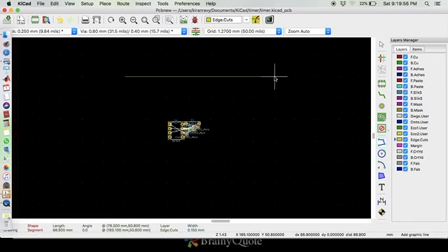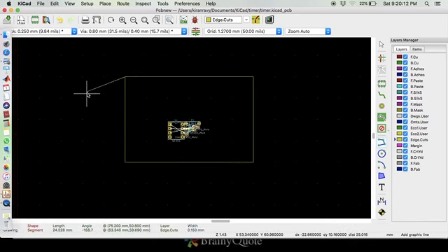Stick on to these points. So I am drawing an approximate size of my board, see, this is just guesswork. You will assume that the dimension of our board will fit into this small area. Okay, so press escape so that line will disappear. Okay, now click on this, now this is the PCB boundary. So our PCB dimension will be this. This dimension is actually in mm, so you can see how much the size of this is.